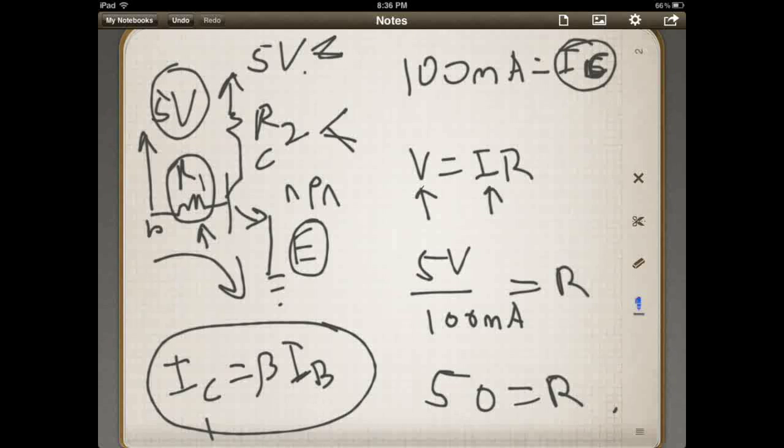So you've got to watch out and make sure you look at your microcontroller to see how much current it can source, because these guys are a current sink hugely, and so you've got to make sure you can source enough current to turn them on and off.